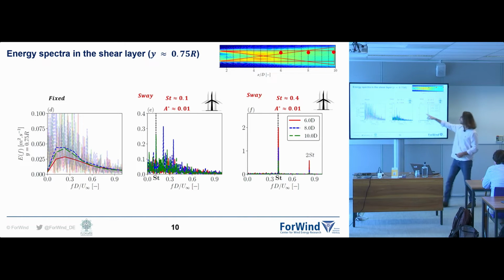And then if we move further, so we increase the frequency, we see that all this range of frequencies merges into one peak, which is exactly the frequency at which we excite the wake. This is quite a nice result, which explains that all the non-linearities in the wake are concentrated into one coherent structure and also some harmonics. And we can actually visualize them.